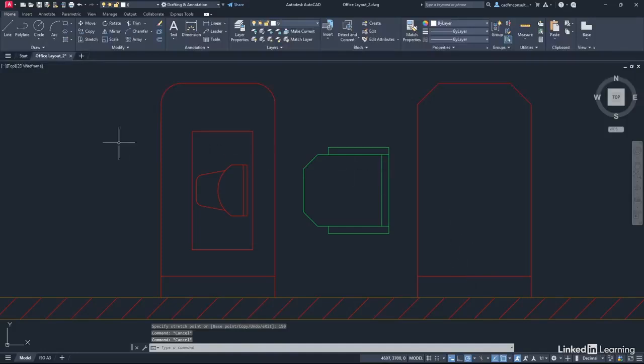And what we're going to do now, we're going to hop to the Modify panel again, click on the flyout here, and you want Trim. Click on Trim, come into the drawing area, hover over this line here, left click, hover over this line here, left click. Can you see you get a little red cross on the piece that you're going to get rid of, and it goes grey, like that, click. And we'll do that again there, click, like so. Then we just press enter to finish.